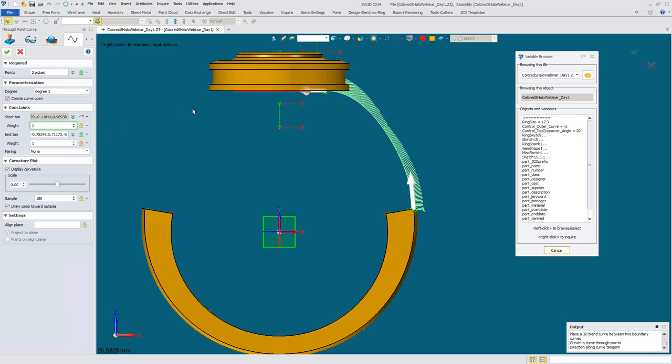Insert variable, put in a control, put in a number that's close to a weight that you think it will be. And then you can play with it. You can have a hell of a lot more controls in here. So, right-click, weight, step size, I'm going to knock it down. Yeah, I'll go there. Okay, so I'm just going to kick this up and I'm watching my curvature. How is the flow? How do I want this thing to flow from the side? Okay?